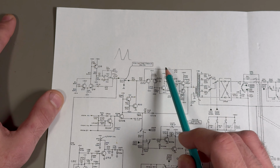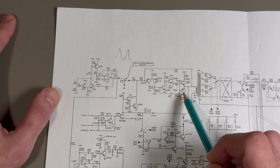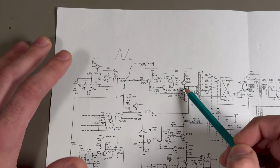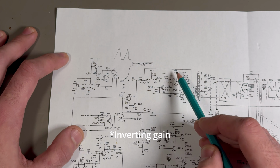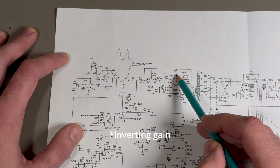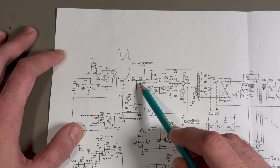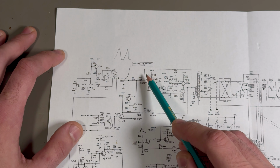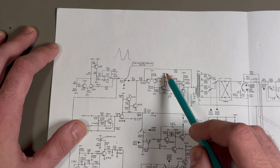This gets amplified. This is a classic Class B amplifier. It was used for audio amps for quite a long time. And it's got some non-inverting gain. It's got global feedback. So R33 and R22 actually form the gain of this amplifier here.